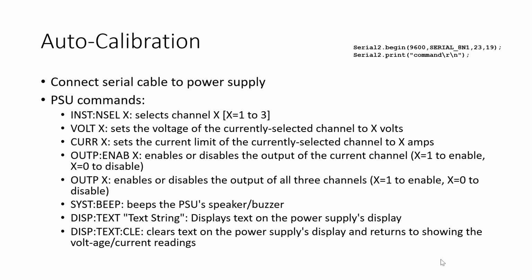And by carriage, I mean typewriter carriage, like the typewriter. This is literally a typewriter, move the typewriter thing to the left and then go to the next line. I have no idea why we're doing typewriter stuff, but you have to do \r, \n, right? Okay, so make sure that comes after every command. There is a command that you have to do initially to establish the connection. That's in the lab sheet.